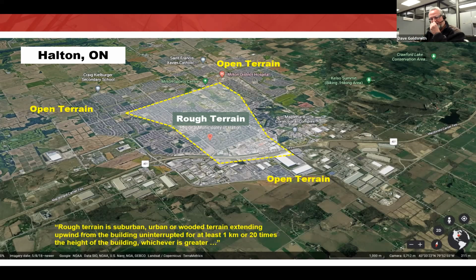Because they cover something like 90% of the circumstances within cities, but they don't cover that 10%. Now that we've got A440S 109, we need to be mindful that sometimes your base window designed to that old standard is not sufficient.